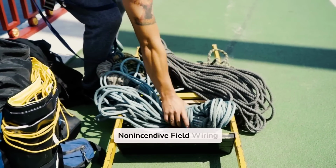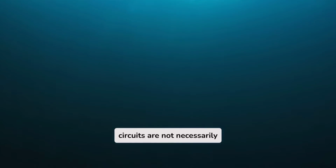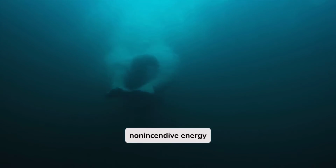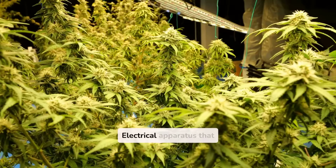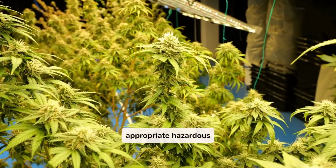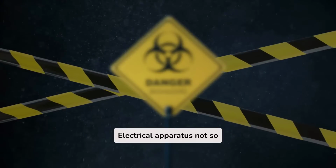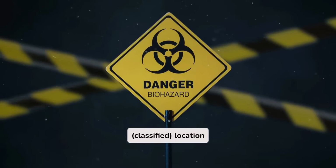Associated nonincendive field wiring apparatus. Apparatus in which the circuits are not necessarily nonincendive themselves, but that affects the energy in nonincendive field wiring circuits and is relied on to maintain nonincendive energy levels. Such apparatus is one of the following. Electrical apparatus that has an alternative type of protection for use in the appropriate hazardous, classified location. Electrical apparatus not so protected that shall not be used within a hazardous, classified location.